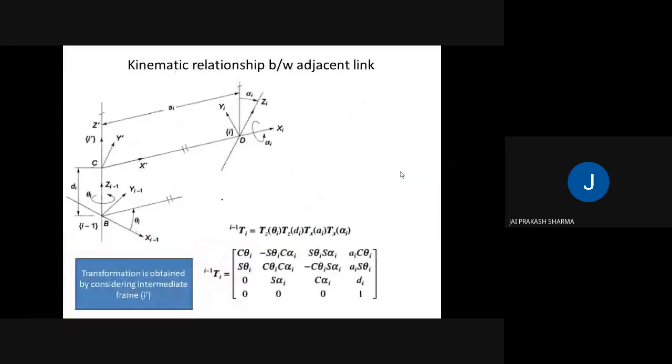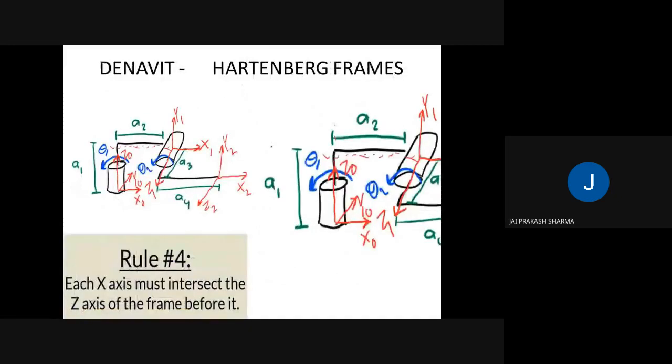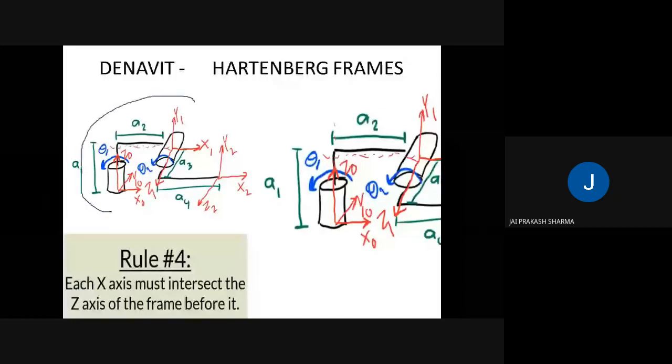robotic arm configuration. Now DH also provides one more rule. Suppose you have two different configurations. With respect to that, I'm going to the previous slide. Over here you can see that for calculating the final tool position, we have to follow the rule offered by Denavit and Hartenberg. In the same manner, if you are going to calculate the final tool position with the help of software, you have to move your previous frame, that is the x0, y0, z0 frame, to x1, y1, z1. So you have to move in such a manner that this x0, y0, z0 frame matches with x1, y1, and z1. This is another rule offered by Denavit and Hartenberg, with the help of which you can correlate two different frames which are generated with respect to two different servos.